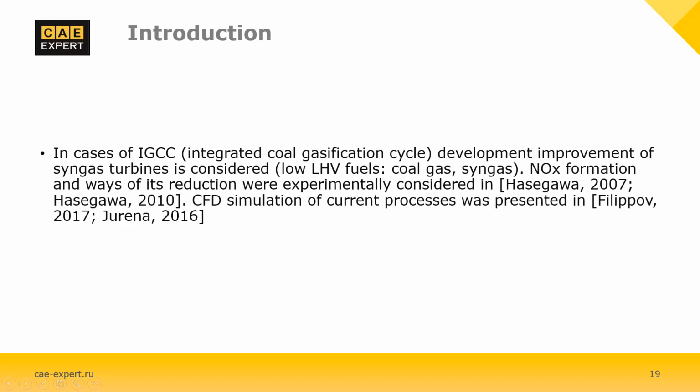from 1986 to 1996. The Central Research Institute of Electric Power Industry developed an air-blown pressurized two-stage entrained-flow coal gasifier, a hot-dry synthetic gas cleanup system, and 150 megawatt gas turbine combustor technologies for low BTU fuel. Of late, the government and electric power companies are promoting a demonstration IGCC project.